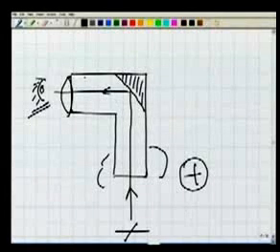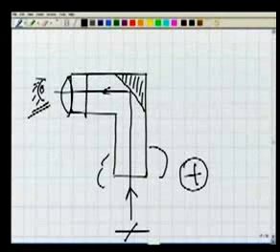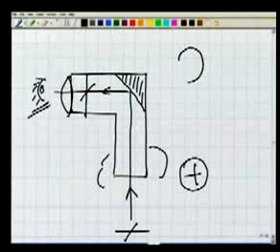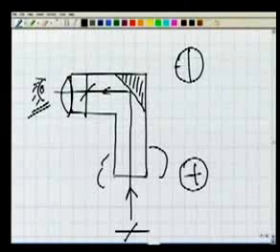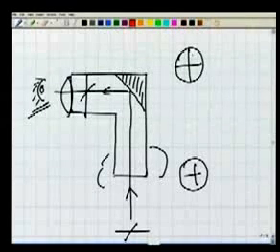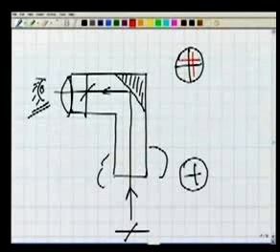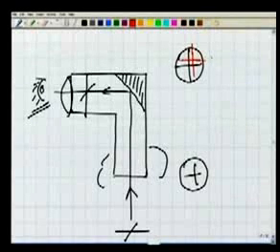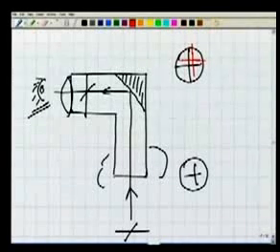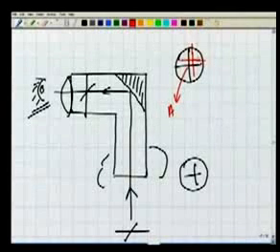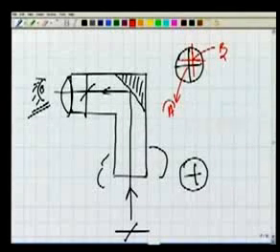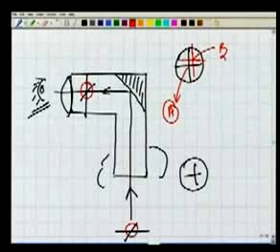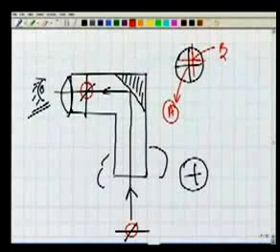Now here in the eyepiece of the optical plummet, again we have a cross wire. So the cross wire of the optical plummet, which may look like this, and the mark there in the ground. Let's say the red line indicates the station there in the ground. This is the station. What our job is, we want to align these 2 points, point A and point B. Point A is the center of the cross wire here. Point B is the center of the mark there at the station. And we want to align these two.